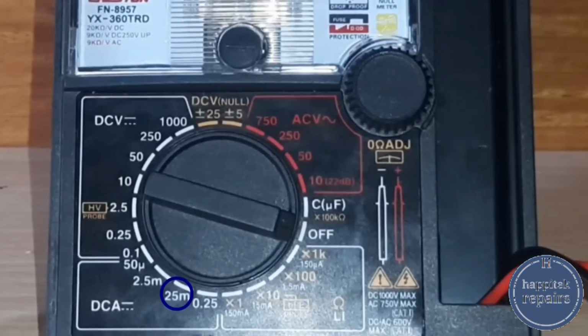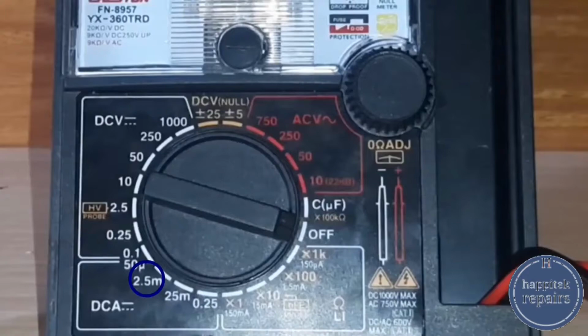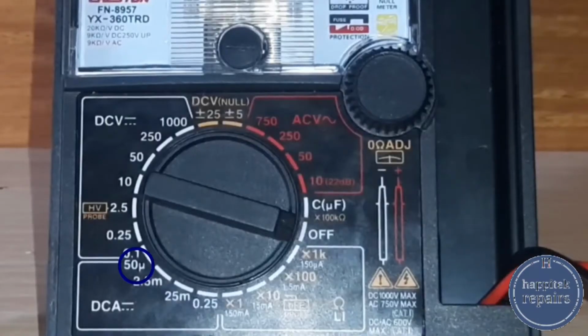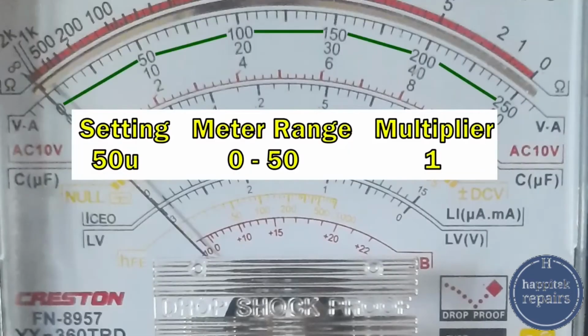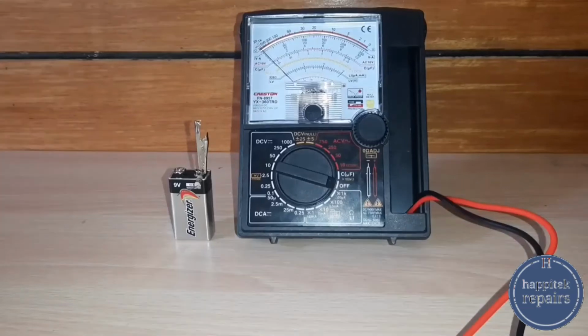The meter range is 0 to 250, and the multiplier is 0.1. For 2.5 milli, we still have the same 0 to 250 range and 0.01 as a multiplier. Also, the value of current will be expressed in terms of ampere. Using 50 micro, 0 to 50 range, and the multiplier will be 1. Current will be in microampere.